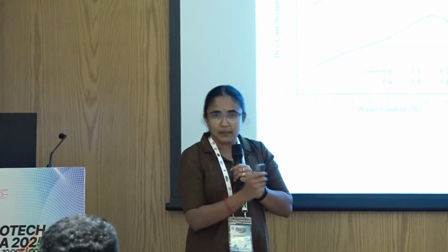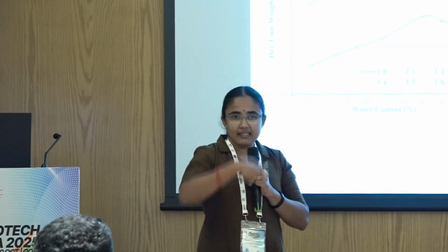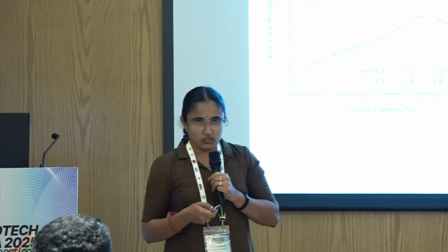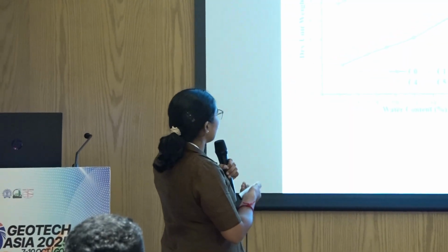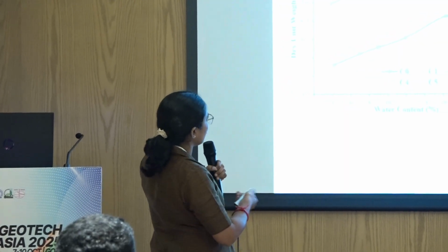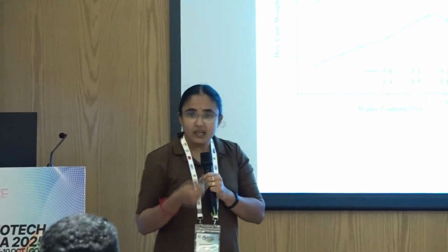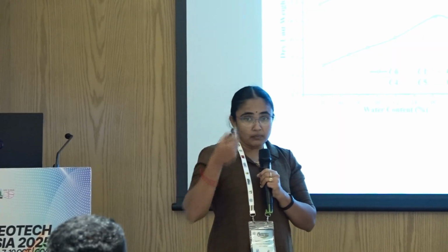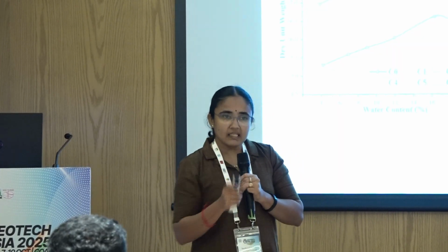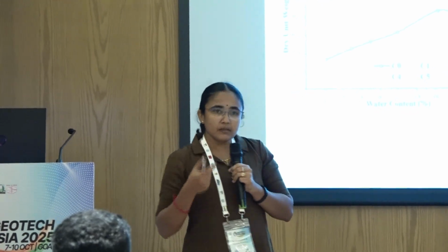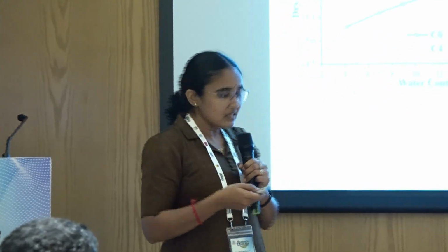So just to increase the crushing, we have increased the number of compaction tests. We have seen that the MDD tends to increase and the OMC tends to decrease, which is a good sign, because in its uncrushed state it created highly non-uniform void spaces because of bridging and ordering. As the particle size decreases, the particles occupy the pores, which increases the density.